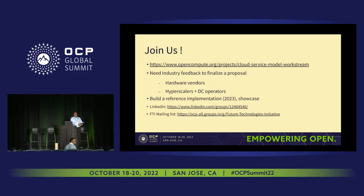Okay. If I can help, the IMA is supposed to be complementary to what the BMC can offer. If we have very fast-paced hardware evolution, some of the features that we would need for the telemetry of the GPUs, let's say the ML equipment, may not be available in the BMC and may not be wired to be collected from the BMC. So the IMA can complement that and collect it and stream it down the same channel, the same technology that the telemetry would collect for any other traditional, classic hardware.